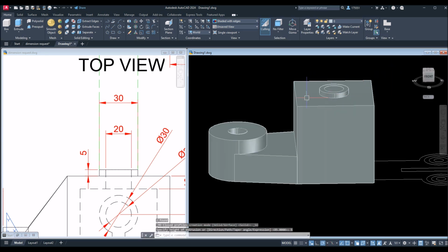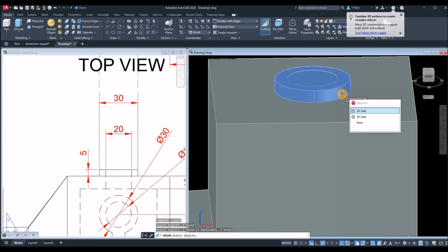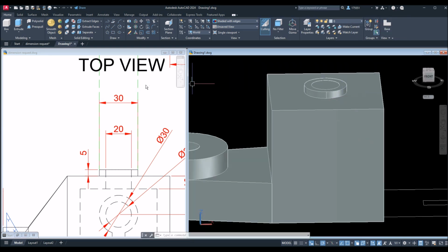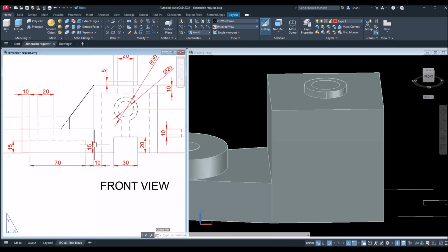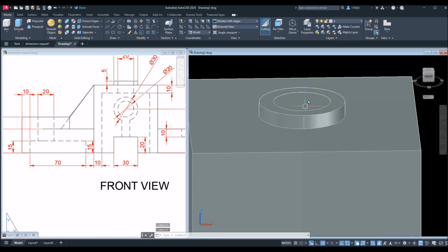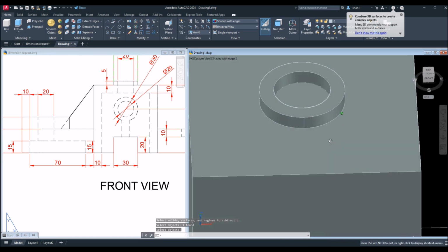Now I'm gonna union the objects, this object and this object here. I'm gonna apply shell, and the thickness of the shell is 10 units as shown here. But first I'm gonna poke a hole through this object here, or subtract. So subtract command, select this object you wanna keep, right click and select this one in the middle.